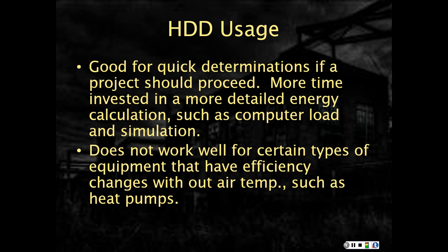Now, how do we use heating degree days? They're good for quick determinations of whether a project should proceed. Again, we use it more for a quickie. Should I do more work on this? Should I spend all the extra time to do a computer load calc and simulation? It's used as a screening tool.